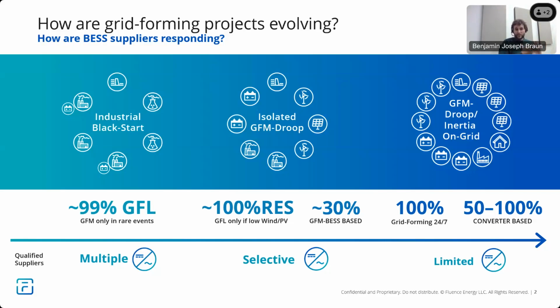You were looking at getting more renewables in the grid, turning off N-1 must run thermal generation to really save fuel, save emissions, save the bottom line for the final ratepayer. And you started getting more and more needs. So these systems now needed to be able to handle many more unexpected events. You had this wild grid outside of the point of interconnection of the battery, and you didn't always know what was going to happen. So you had to plan for a lot of different contingency events.